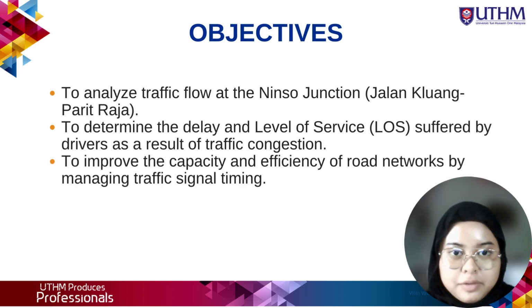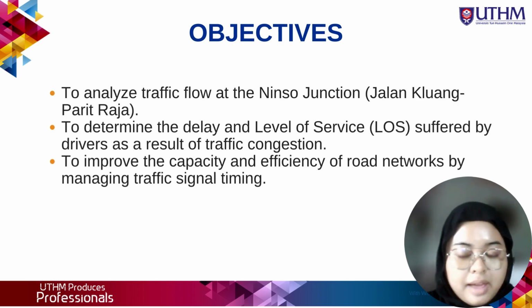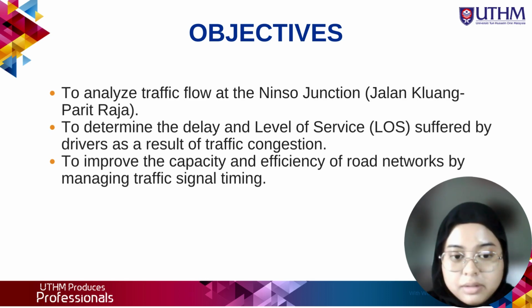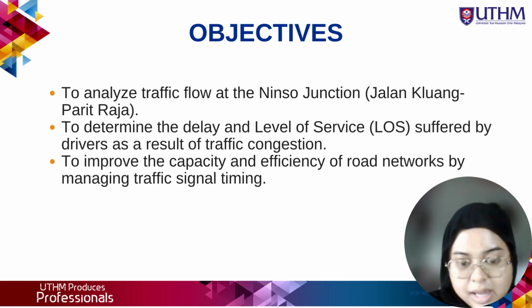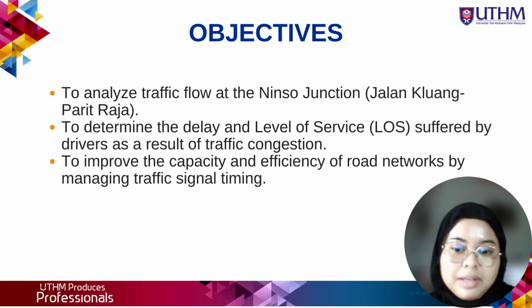Our objectives for this group project: the first one is to analyze traffic flow at the Ninsu Junction, which is located in Jalan Keluang to Parit Raja. The second is to determine the delay and level of service (LOS) suffered by drivers as a result of traffic congestion. And the last one is to improve the capacity and efficiency of road networks by managing traffic signal timing.